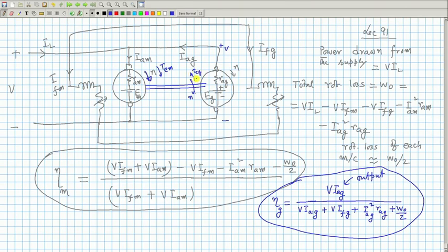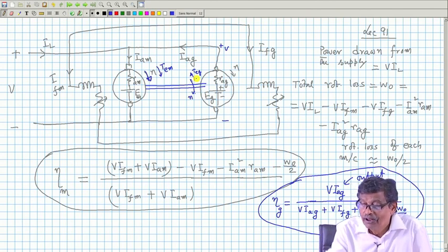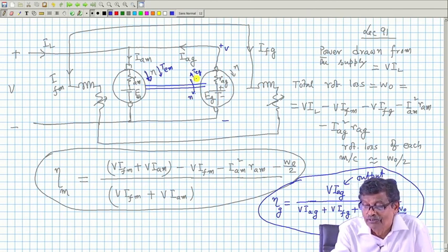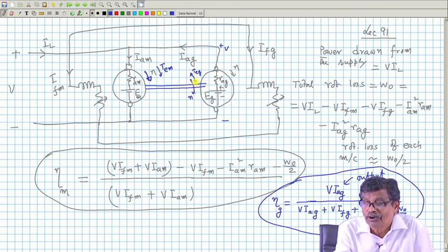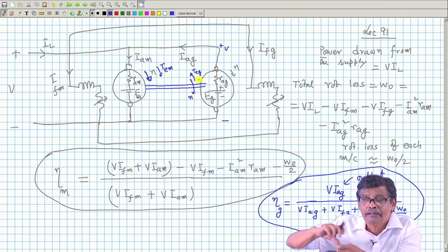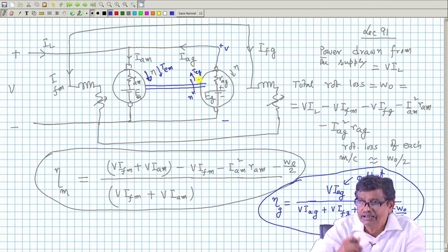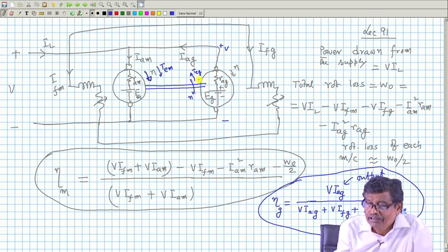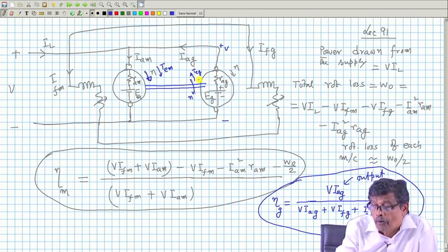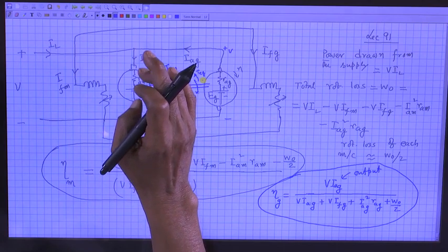For this, the motor does not know; it will only see that on the shaft there is an opposing torque, that is why it is behaving like a motor. It will draw more current, whether this torque has come by direct belt loading, the thing I discussed, it cannot distinguish. It will see, okay, on the shaft there is now some opposing torque, draw more current.